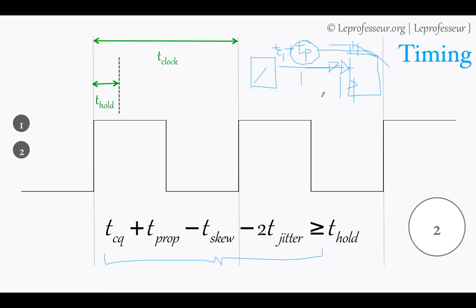You take each path wherever you see a timing violation, and if you see a hold violation, you can insert buffers in that path and run the session again for both setup and hold time till you get both correct. So these are two important equations for setup and hold time, and your design must satisfy them.